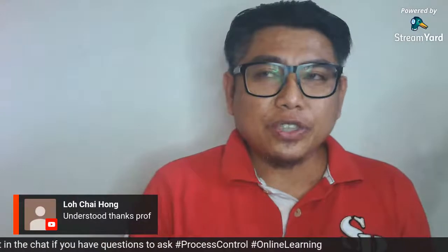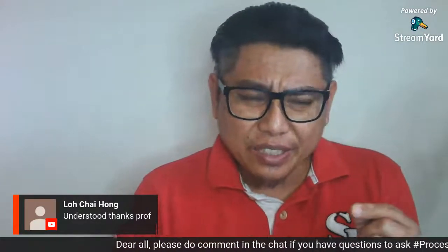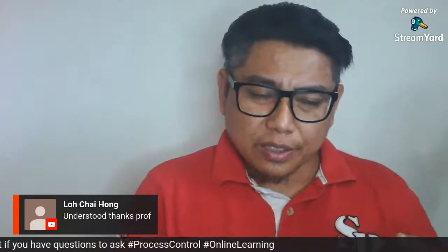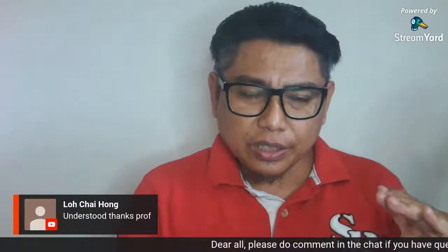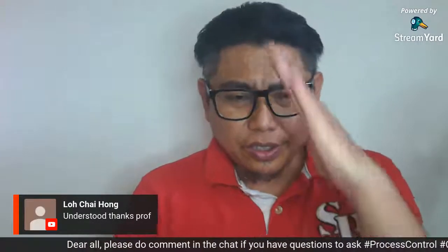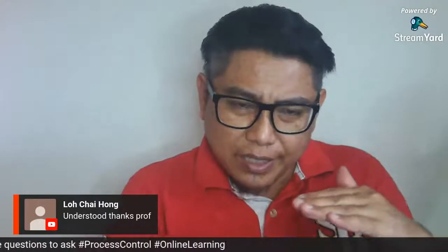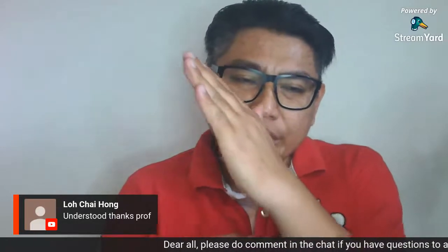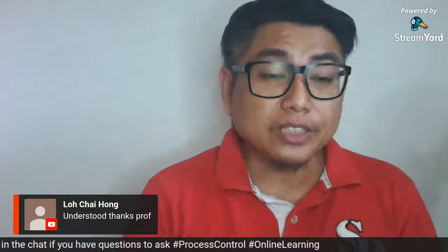Okay. The first order plus time delay, or what we call the process reaction curve, is basically different from the first order. There is a slight curve at the beginning of the increment. For first order, it goes up straight away. If you apply a step change to your input, the first order goes up straight away. But for the process reaction curve, or first order plus time delay, there will be a slight delay and a curve response before it starts to increase. And that's how we differentiate between the first order and the first order plus time delay response.